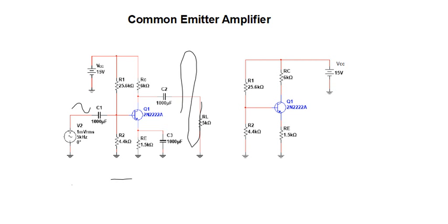When I open circuit C1 and C2, that really chops off the AC supply and the load resistor. And when I open circuit C3, it doesn't chop anything else off, but it opens up itself, so it just disappears for the DC. So I end up with exactly the same circuit we had last time.